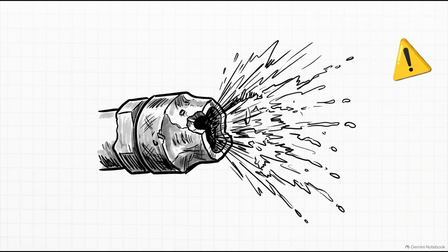The job task analysis specifically calls out nozzle condition as an exam topic, and here is exactly why it matters. As an inspector, you've got to realize that even if a worn-out nozzle still technically spits out material, it is producing a much poorer spray pattern. It messes with the stream shape, the velocity, and how the water is distributed. A degraded spray pattern directly compromises the quality of your placement, which inevitably leads to poor compaction and those dreaded voids hiding behind the rebar.